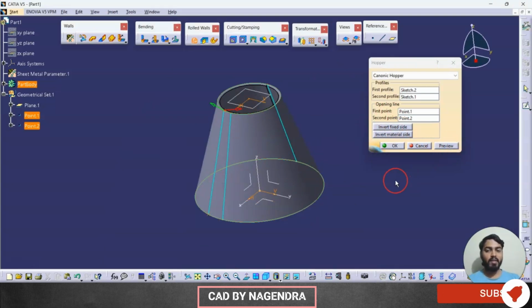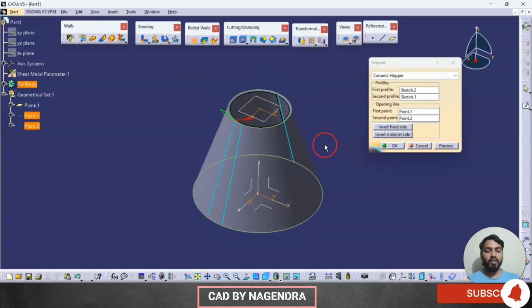So what does this fixed side mean? If you want to create this shape of sheet metal, usually we take one blank sheet, then bend it like this, cutting the excess material. Later we join it at some particular point. That joining point is the one where we have created points. So we only need to create points, which means wherever the joining of two sheets is going to happen, that is the selected point where we created these points. I'll keep invert material like this, outside.